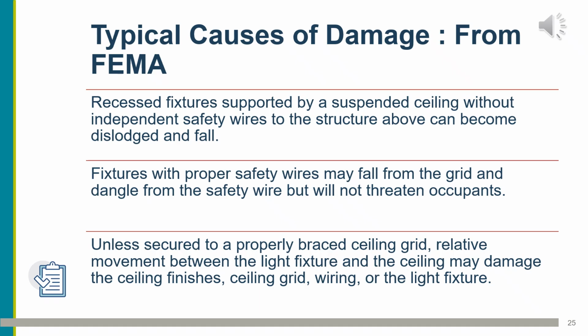Egress by occupants, ingress by emergency personnel. And unless they're secured to a properly braced ceiling grid, relative movement between the light fixture and the ceiling may damage the ceiling finishes, but it won't hurt the people or hinder ingress or egress.